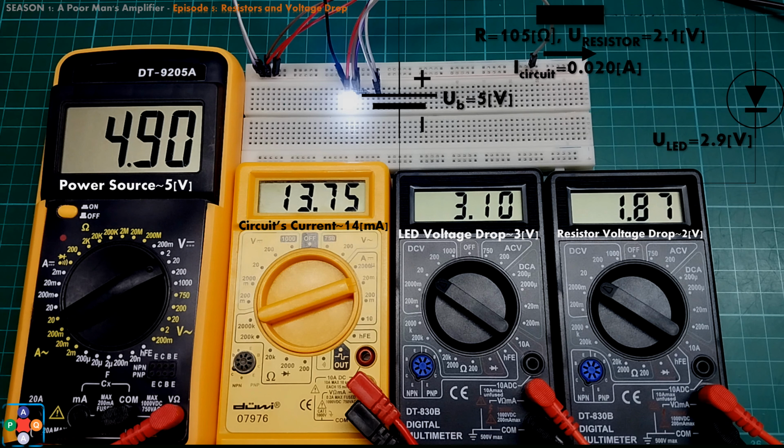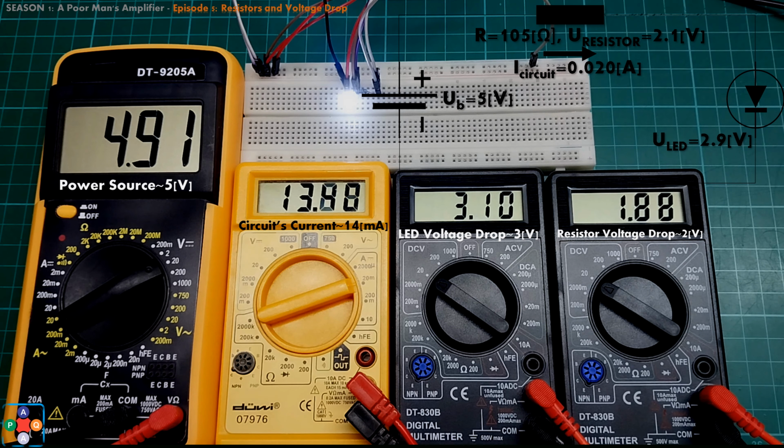For a short period of time, this will not cause problems, but if we leave our LED to run for hours and days, that excess amount of heat that LED generates due to increase of current in circuit, will in time damage the LED diode, causing it to lose brightness, and at the end, it will burn out. On the other hand, had you followed the rule of thumb, the higher value resistor would have no problem in regulating the excess of current, and it would have protected our LED diode from overheating and burning out in the end. The video playing in the background during this narration is our prototype of circuit schematic used in this video.